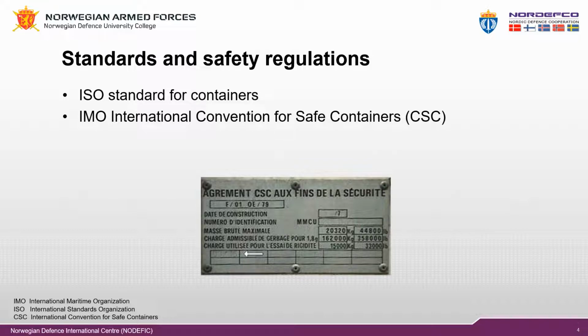The Convention of Safe Containers is an international regulation developed to cover containers used for international transport. The containers must have a valid safety approval plate called CSC plate. This is the only guarantee that the container is safe to travel. Only containers transported via air are exempt from this regulation. The convention that introduced the CSC plate aimed at achieving the highest possible level of safety of human life in handling, stacking, and transportation of containers.